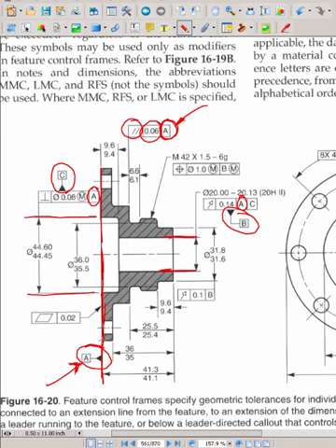So first of all, we look at surface A, which is the entire back surface of this part, and it says that this surface, since this thing has no arrow, it means this surface right here is parallel to this surface within a tolerance value of 0.06. What it means is we are creating an imaginary boundary that is 0.06 wide, and that this surface has to fall between it.